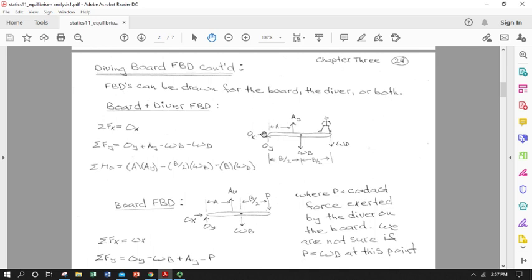So that's nice. You can pick any point on that body and write an expression for the total moments about that point. And remember, moment about a point is every radius crossed into the force, looking at the line of force and the radius from the point of interest. And then if there are any direct couples that are being applied, you add those in. So let's see what they are here.